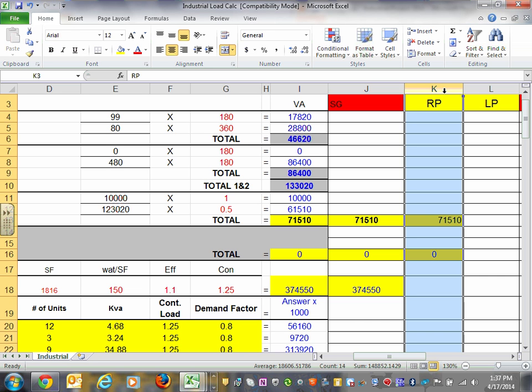The second column is allocated to your low voltage panel, or I call it receptacle panel, but call it P1 or LP1, whatever you want, just to identify it by function, call it receptacle panel. And you agree with me that this chunk of receptacle load will be seen by the main switchgear, and at the same time will be seen by the receptacle panel.